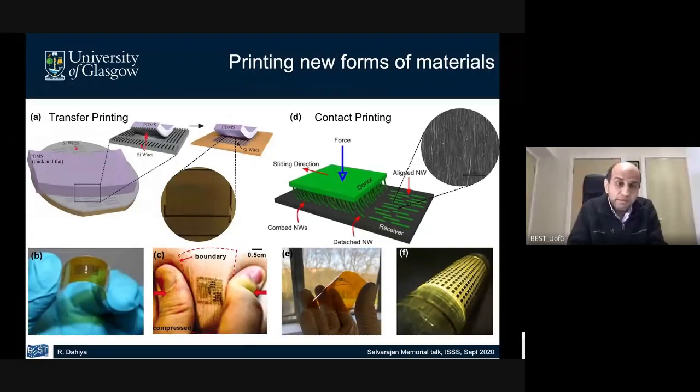So with organic semiconductors, it is quite challenging to achieve that kind of performance for two reasons. Number one is the low mobility. Number two, the technology that we have does not give you transistors with shorter channel length. And both are important. They both contribute to faster transistor switching frequency. In this regard, we are exploring two approaches: transfer printing approach and contact printing approach.